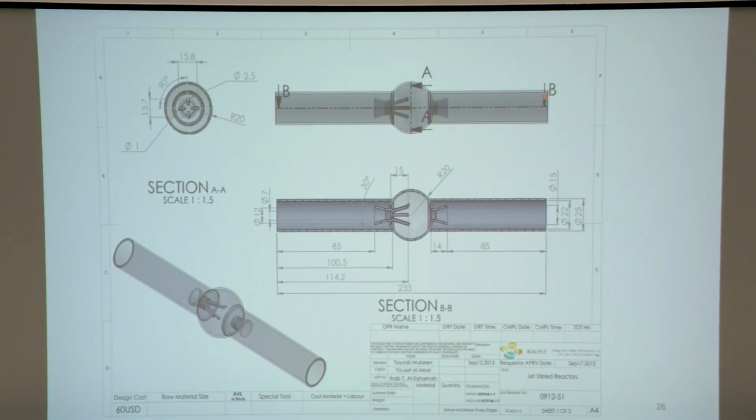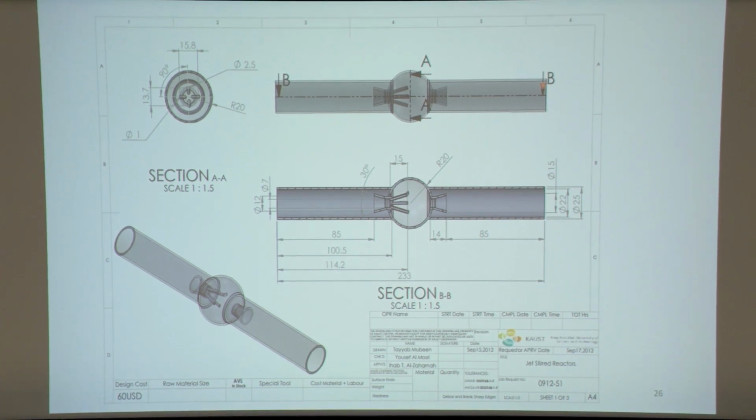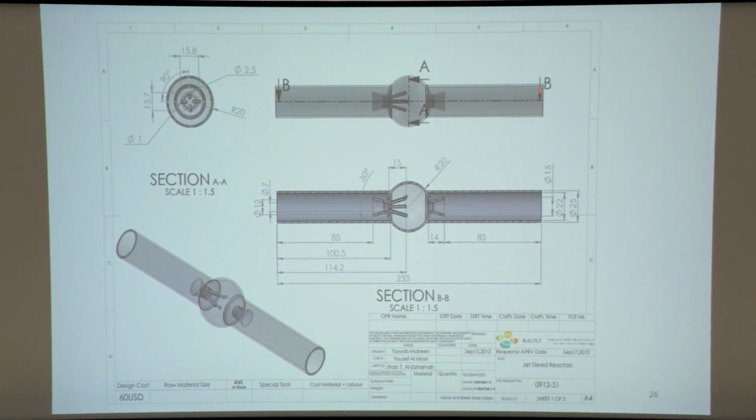I think now what many people do is they just design the reactors in CAD software, and then you do a CFD simulation. It's a pretty straightforward non-reactive CFD. Then you can do your residence time distribution experiment numerically. You inject a tracer in your numerical experiment based on the geometry, and you see what residence times are required to get into a well-mixed regime.